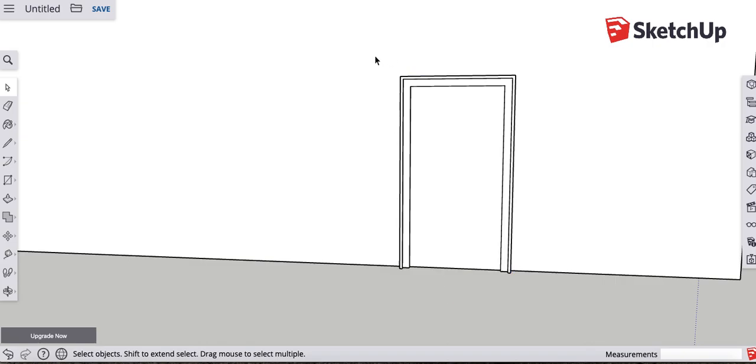But look at how I selected the door. Notice how I went from left to right, my selection window, left to right, and I select the whole door. Okay, look what happens if I don't select the whole door. It selects nothing. When you go from left to right with the selection tool, you have to select entire lines. So I have to watch, if I select all the way across, it'll select 3 of those horizontal lines because I selected all of them in my window. Okay. If I want to select the entire door, I go left to right, and I select all of those lines.